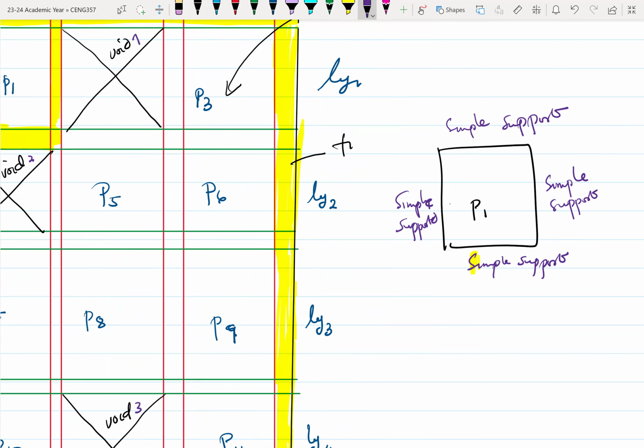All right. So anytime a support at a slab, or at the end of a slab, which normally is going to be a beam, because we are dealing with solid slabs, which is a beam-slab conventional design, so that's the support at the slab. If it doesn't have any adjoining slab on the other side of it, or where you are not explicitly stating that the beam is a fixed support, then the assumption is that those beams are simple supports, or they are the pin support for the slab.